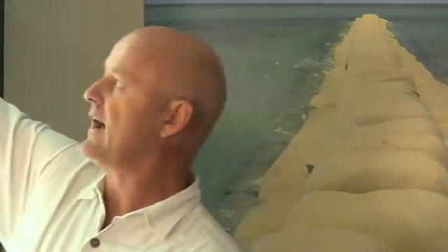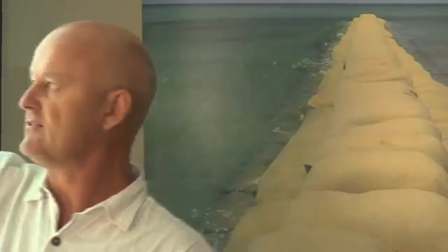Another really common mistake I see: bathymetric charts use a different datum to land surveys. They normally work to chart datum, for the part of the profile underwater, whereas the land surveys usually work to AHD, Australian Height Datum. So that's a very common mistake that I've seen during projects, and it's worth noting that.